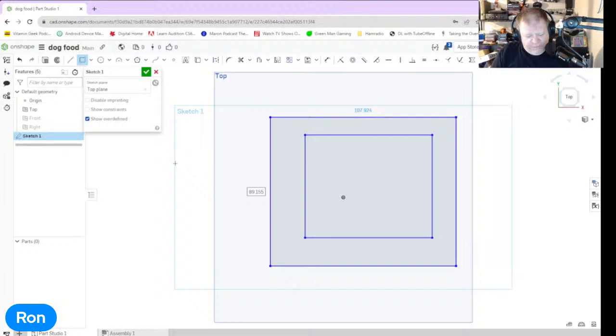Okay, so we are dealing with a box that's 89.91. So we'll say 90 by 90. So we'll go 90 by 90 on this design. Give and take, I want a little bit of extra movement. I'm thinking 90.25 might be just the right amount to give it a little bit of play. So put this back in here. Turn this off. So we're going with 90 by 90 here.